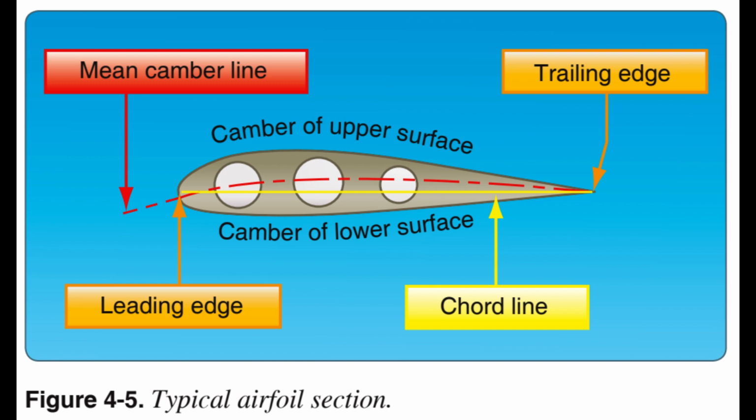As the airstream strikes the relatively flat lower surface of a wing or rotor blade when inclined at a small angle to its direction of motion, the air is forced to rebound downward, causing an upward reaction in positive lift. At the same time, the airstream striking the upper curved section of the leading edge is deflected upward. An airfoil is shaped to cause an action on the air, and forces air downward, which provides an equal reaction from the air, forcing the airfoil upward.